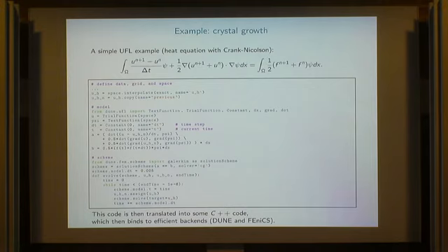Good, so this is the interesting part, I think. This is the UFL code, in which we code up this problem. We need a trial function, that's going to be the U^(n+1), and the test function, that's the psi here. We need the time step, delta t, and for the right-hand side, for the source terms, we need access to the time. And then this A that we have on the left-hand side is covered here in A, almost in a one-to-one fashion.